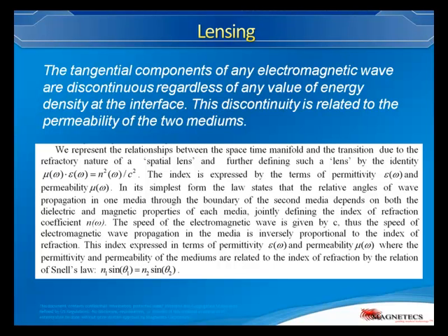We did the same thing in our electromagnetics. We created two permeability rules. We created a calculator that allows us to take a very low permeability, like 10 on the ring, while the pole faces of the magnetic field generators have a permeability, mu, of 1000. This ratio produces an angle proportional to the shift, so you see that the shift is emulated in electromagnetism. We were able to create fields that are highly dense. The flux density is very, very high based on our demand. Otherwise, you would expend a massive amount of energy to try to do the same job. Next, please.